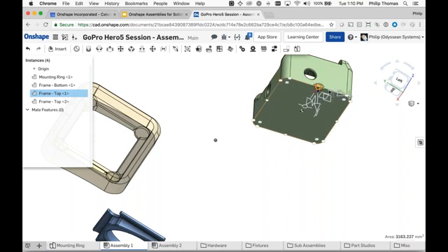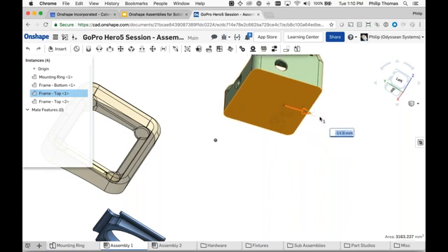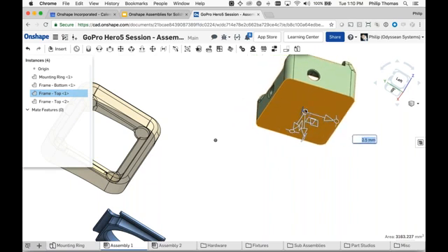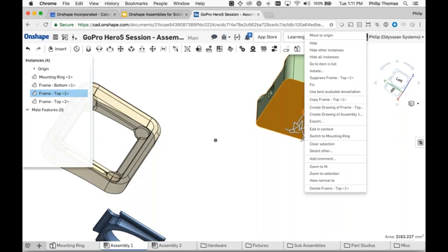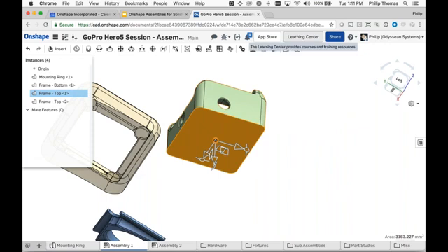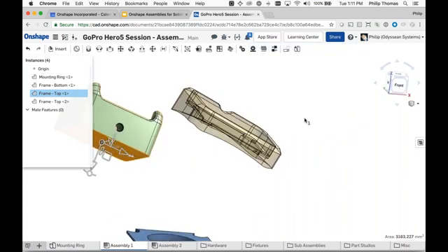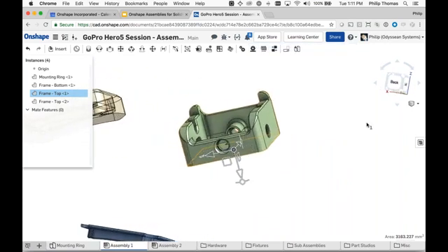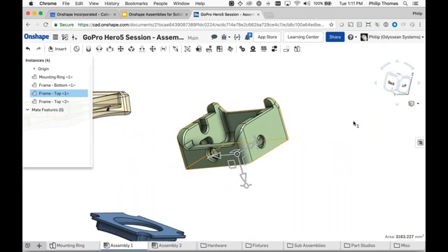We're going to talk a lot more about these points in a moment, but for now, just imagine there's sticky points, and here's one at the centroid of the face, and now that manipulator is attached to the centroid of the face. The manipulator still works in exactly the same way, except that the center of the manipulator is at the centroid. And I can now do things like right mouse button over the origin of the manipulator and say, move to origin.